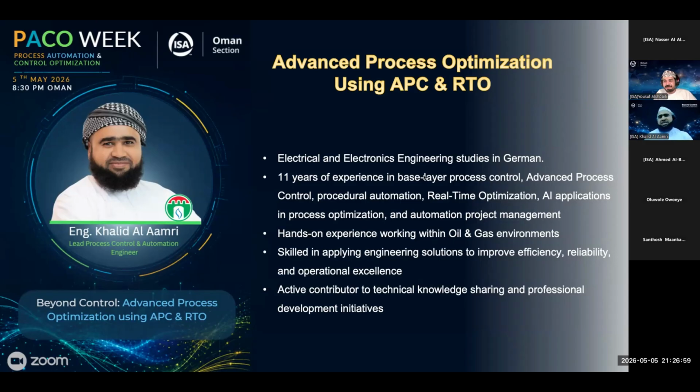I haven't done a green plant, I don't have that experience, but I can imagine that you'll need to step test. But as a starting point, your first principles model will need to be a dynamic model. The steady state model is not enough. If any one of you has done that before, please feel free.